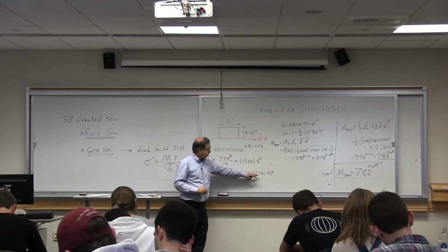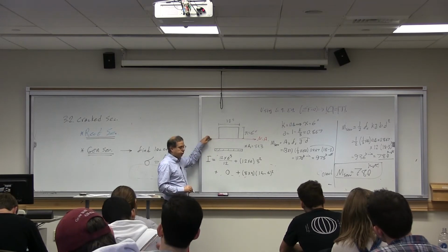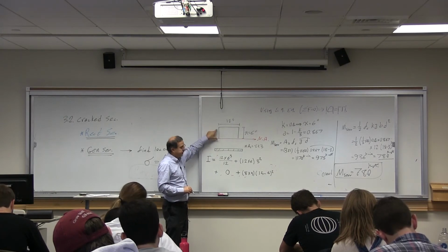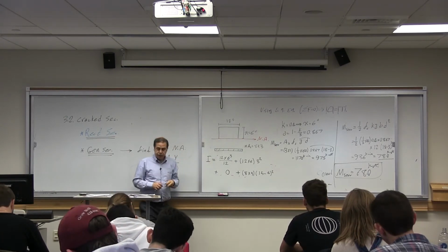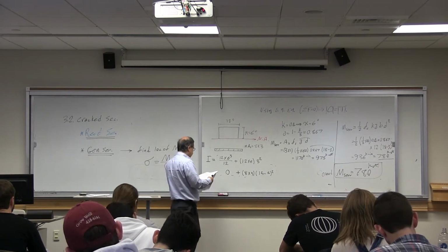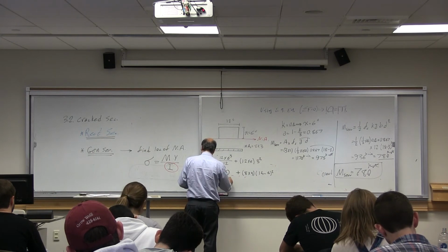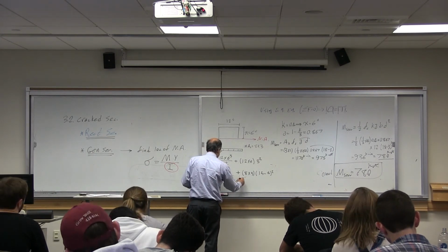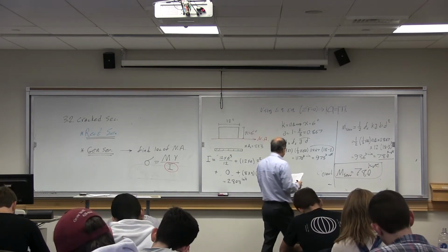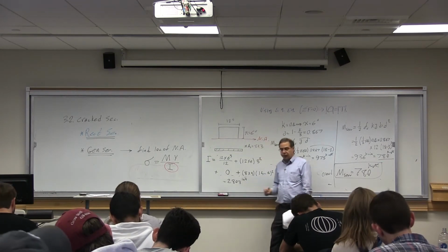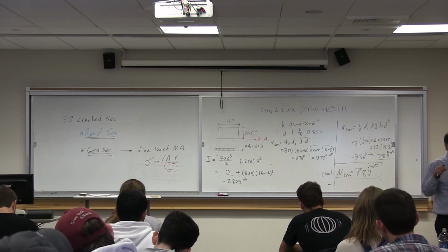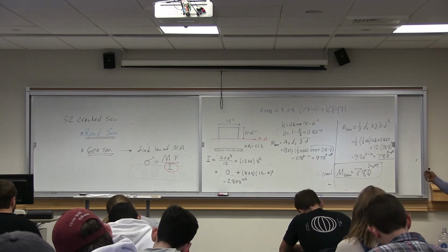This is the distance between the rebar and the centroid or neutral axis, which is d, which is 15 minus 6. If you do this calculation, you would get moment of inertia equal to 2808 inches to the power of 4. You can see that this moment of inertia is significantly less than the moment of inertia of the uncracked section.